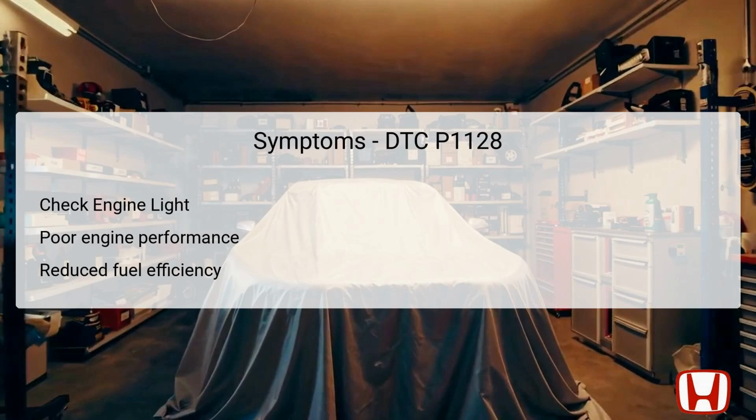The symptoms associated with DTC P1128 often include the illumination of the check engine light on the dashboard, signaling an issue that needs attention. Additionally, you may notice poor engine performance, including hesitations during acceleration or difficulty maintaining speed.